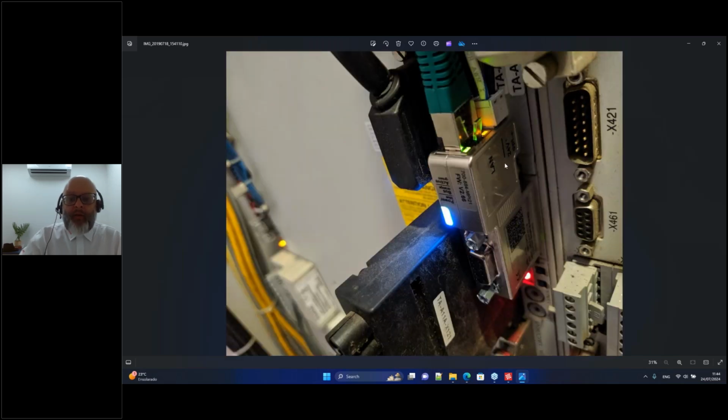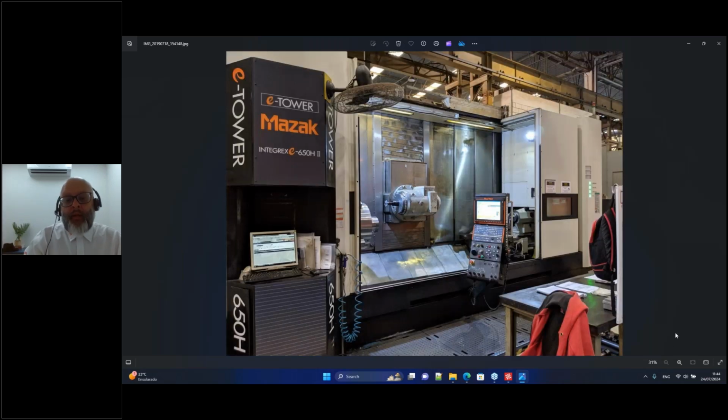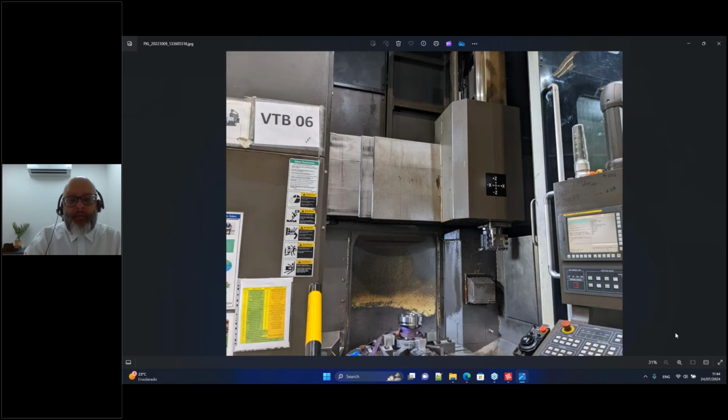So this is another look into the adapter, getting data from the machine PLC, clean installation, just plug and play, and then remotely you can pull the data you want. If you have the electrical diagram from the machine, very easy. Don't need to know electronics in depth, because the electrical diagrams are very clear. They say this is the signal of the pump, like I showed you. So you don't really need to have skills in electronics. I don't have it, and I never had any issue implementing this.